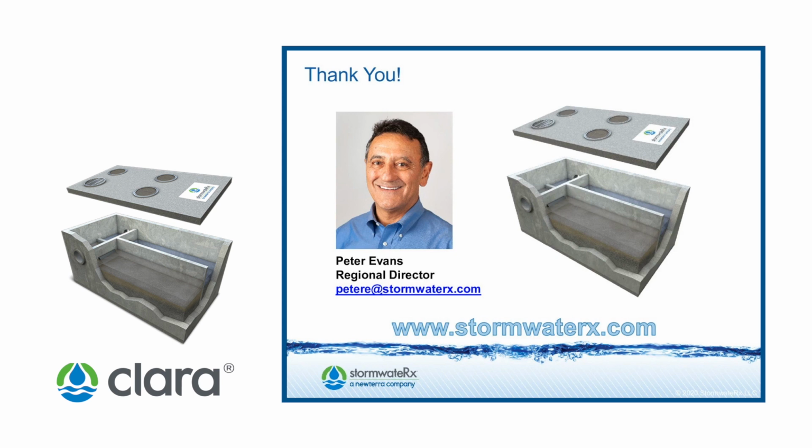All right. Well, thank you, Rob. Steve Fisher, thank you for joining us today. You had a question about how much efficiency is lost after the 6-inch media is removed. I guess I didn't make myself clear. Once that 6-inch layer of media is removed, it's replaced with new media, Steve. So there will be very little or no loss in pollutant removal efficiency or TSS removal efficiency.